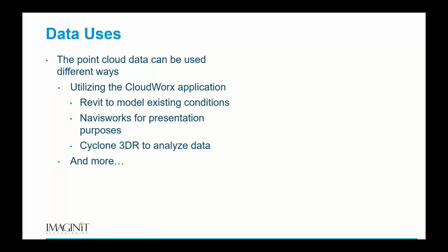If I take it up a level and I want to use it in Revit, again, I bring it into Revit, which is a phenomenal program, but let's be honest, it is a new construction software, not an existing condition software. And everybody's kind of chuckling because you know I'm right. Will it work? Absolutely, 100%. But it doesn't like lines slightly off kilter, etc. So we can use the floor plan tool, the same floor plan tool that's in AutoCAD. I find those walls, I hit send.